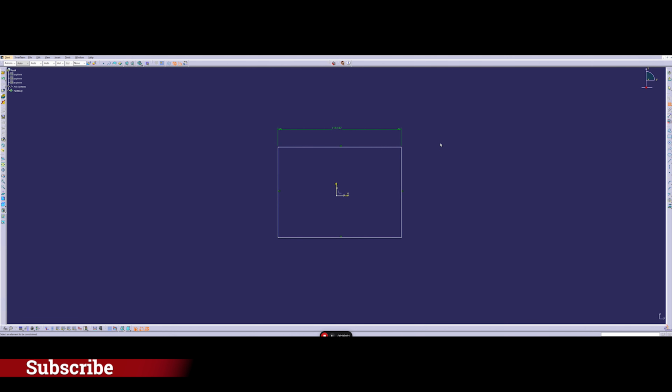So here you see that I get the dimension of my two-dimensional design, and here what I can do is click the dimension, then I can change my dimensions down here. So for example, if I want to go for 120 millimeters, then I can change it from there.